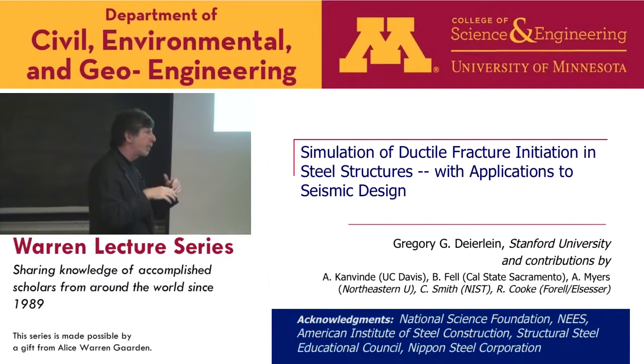Now, this void growth is one mode of material fracture. If you say, well, can you take the material and just infinitely shear it? The answer is no, but there's another mechanism at work there, which void growth doesn't capture. Just like if you get to a very sharp crack with a low toughness material, you might find that brittle fracture will occur before void growth. So I think, and others have said this too, the cutoff for ductile fracture is around triaxiality of 0. Some say 0.2, but we like the value of 0 because frankly, there's not a lot of data down in that area.